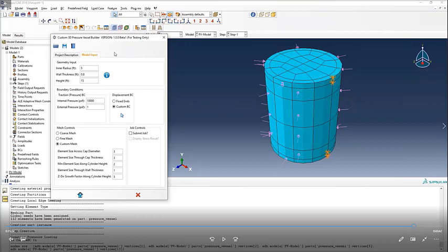Thank you. Is there any way to generate SFD and BMD of a structure in Abaqus? Shear force diagram, yeah. Generally, there are output variables which allow you to develop the shear force and bending moment diagrams.